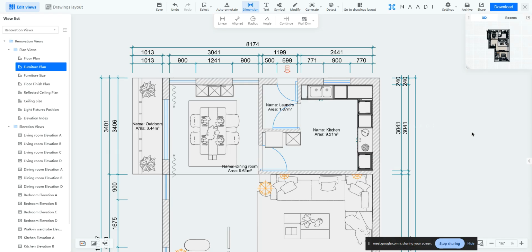You can manually add those dimensions. Okay, you can add it here itself, we'll be talking about it, but those are the scenarios I'm telling. Because of these requirement differences, about 90% of your dimensions are generated, but the remaining 10% of missed dimensions, depending on your organization standard, need to be added manually.